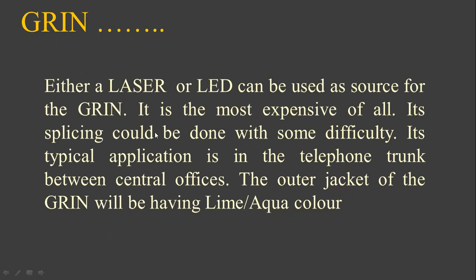Its splicing can be done with some difficulty. Its typical application is in the telephone trunk between central offices. The outer jacket of the GRIN will have lime or aqua color. So this is about graded index multimode fiber.